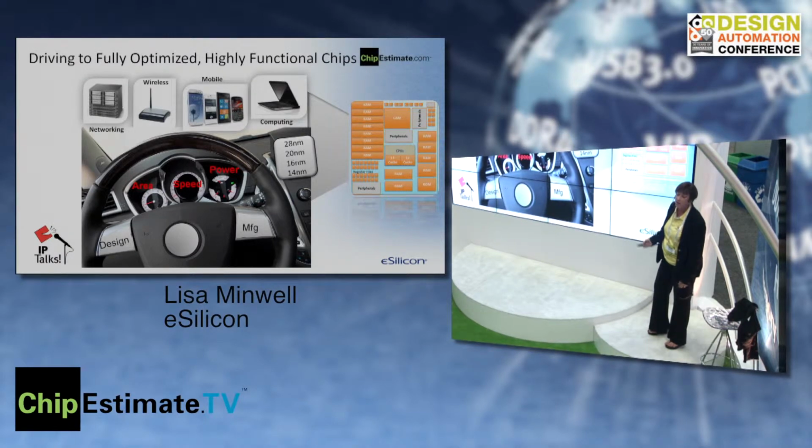So if you look at your chip, that memory content is growing and growing, and you're having to manage that. At the same time, you're dealing with your technology that's reducing from 28, which we understand pretty well, but now we're looking at 20 nanometer, 16 nanometer, 14 nanometer, and then you've got, oh, is it FinFET? Is it FDSOI? What decision is it that I'm going to make on my process, and how do I make that decision? And then with that, how am I going to actually get to the power, the performance, the area that I need for that particular chip and be able to manufacture it? So that's really what this talk is about. It looks at the challenges as you're in this driver's seat trying to make those decisions, and sometimes you actually might need some help.